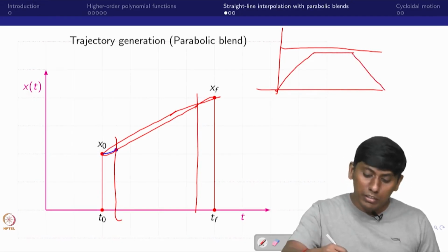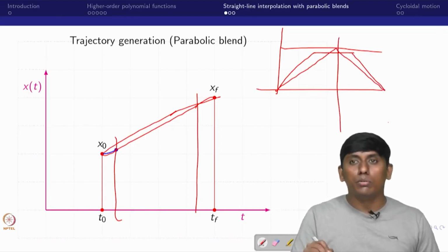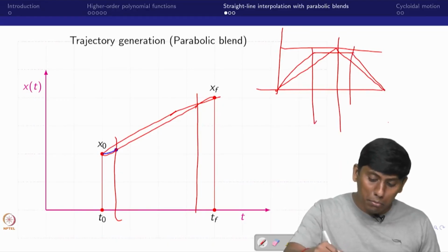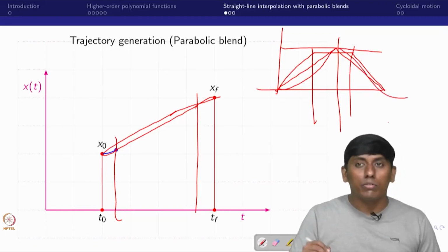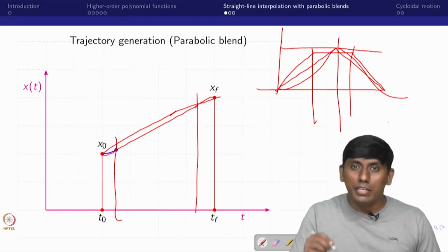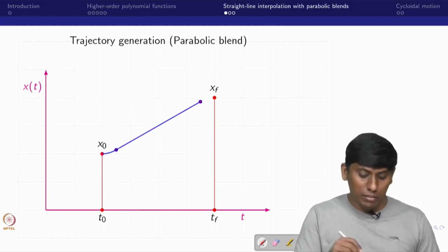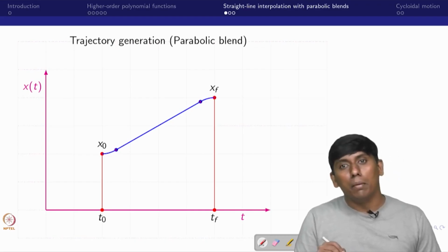Okay, so even this can go like this also. So then this would be what you call the uniform acceleration and deceleration case, but in this case there is a parabolic portion that will come. Here, with the parabolic, there is no blend, so it is going to come in the acceleration curve, that we will see in an upcoming slide. Now you can see this is a straight line, so this to this is a straight line, after that again you make it a parabolic.